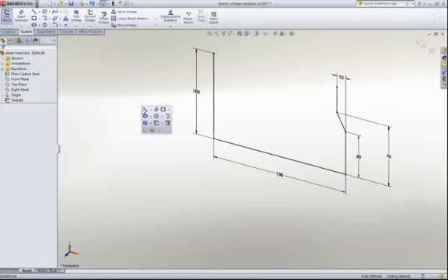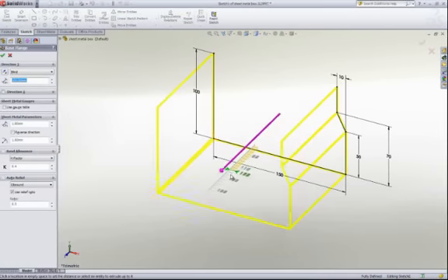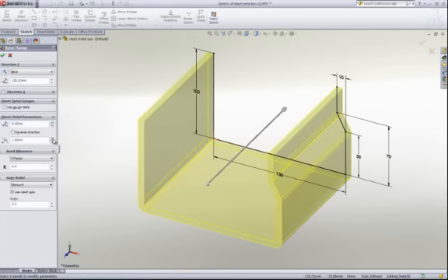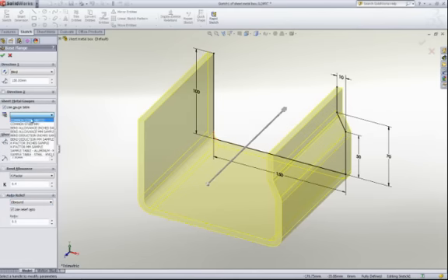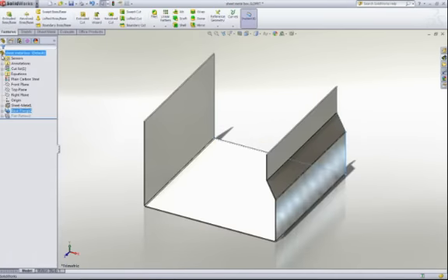Material selection should be your first consideration. In sheet metal design, we are often forced to adhere to certain requirements, such as standard materials and in-house standards for manufacturing and tooling. You need a simple way to make sure you comply with those standards. SolidWorks offers a customizable gauge table, which contains only the materials, thicknesses, and bend radii that are readily available in our shop, so there's no need to look it up each time, and you'll keep tooling costs to a minimum.